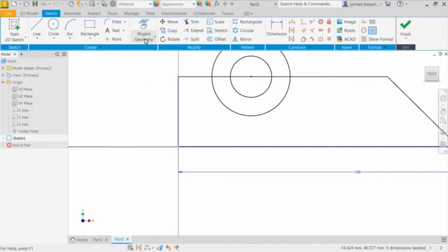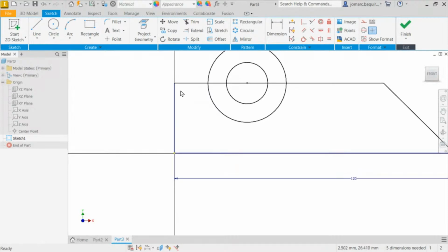What is actually indicated as 25 is not actually these points. So imagine if this is undergoing QA, I have a caliper and I'm going to measure these two distances. It's actually the caliper will land on this line and this line.